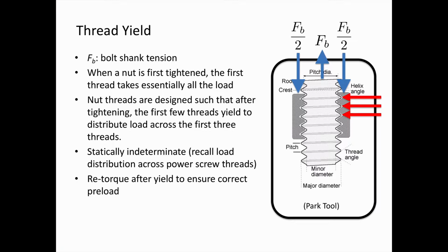So after tightening and yield, the tension relaxes, and it's important to retorque the bolts after this happens.